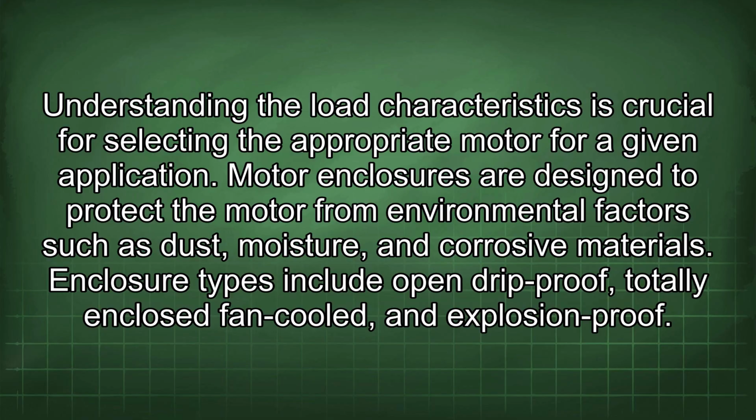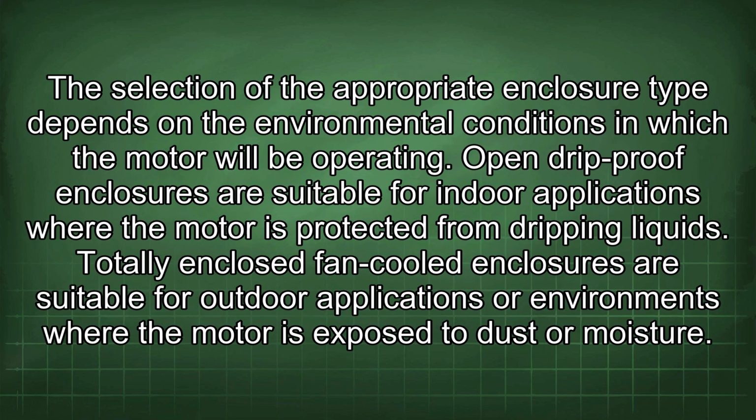Motor enclosures are designed to protect the motor from environmental factors such as dust, moisture, and corrosive materials. Enclosure types include open drip-proof, totally enclosed, fan-cooled, and explosion-proof. The selection of the appropriate enclosure type depends on the environmental conditions in which the motor will be operating.